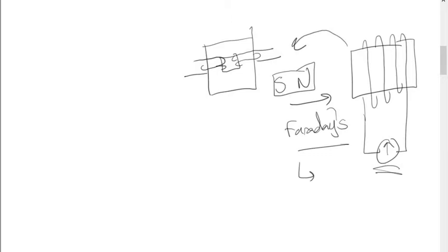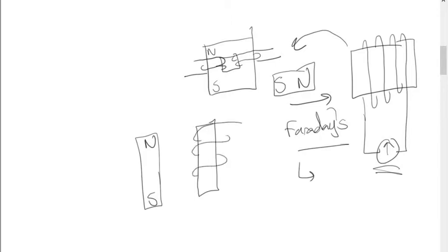If we were to draw it in separate segments, what the primary coil does is it creates a magnet along this end, north and south. And the secondary coil is like another piece of soft iron, and it induces a magnetic field through this. Now, according to Faraday's law, you'll only get an induced EMF as long as there's a change in flux linkage.